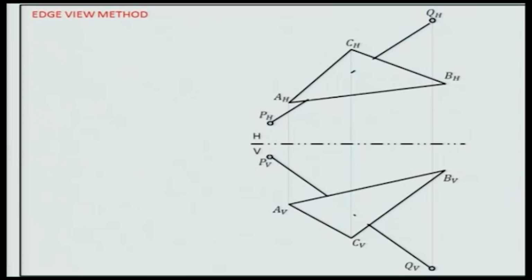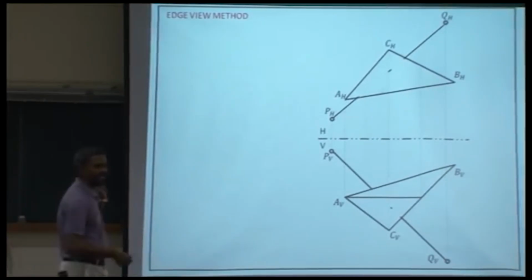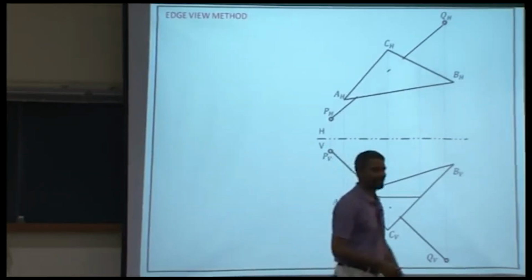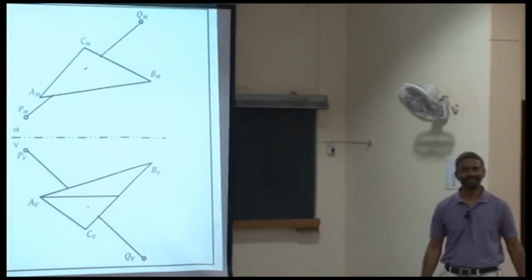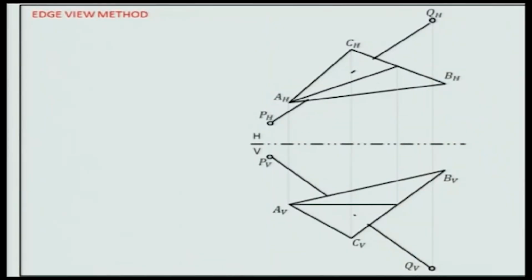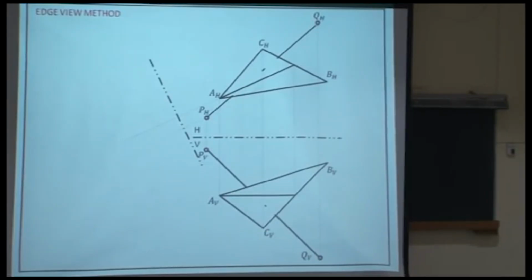Another example, plane and a line. Edge view method. Horizontal. By the time we are done with the lines and planes, you guys are going to be so adept with this method that while you're sleeping, you'll be like, yeah, horizontal line, true length, hinge perpendicular to the line of true length, shoot projections out, measure distances from where?